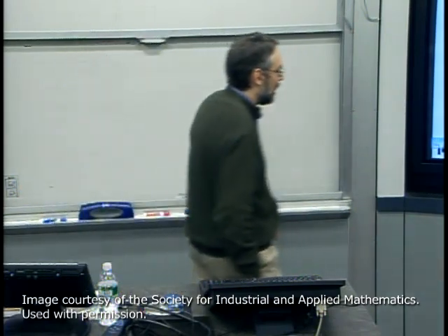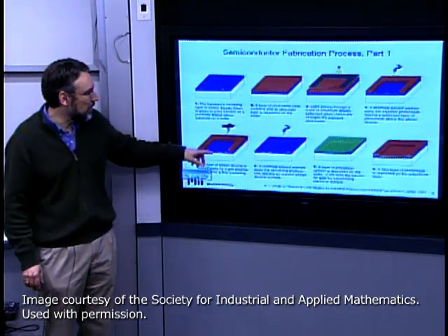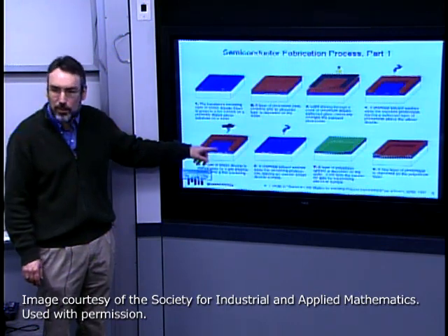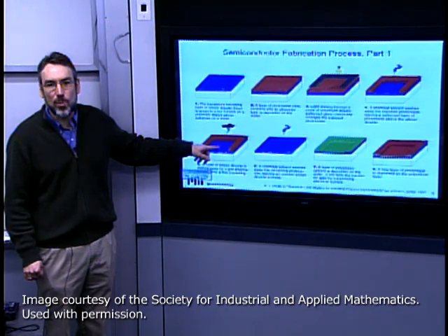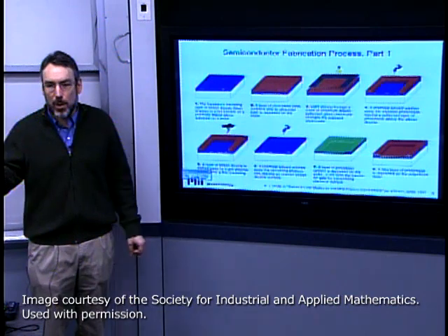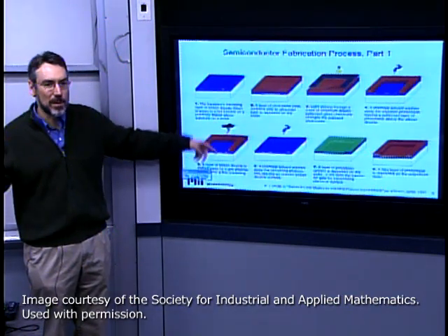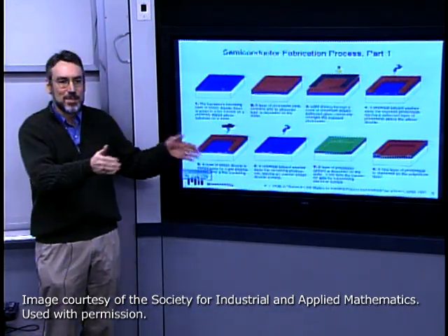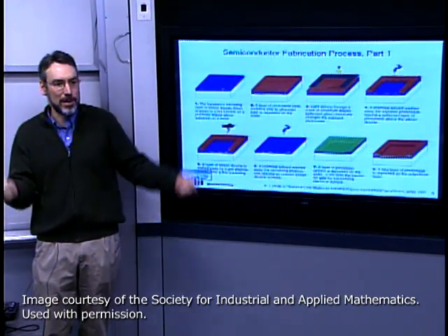At present, at least, and there are some additional reasons why one wouldn't want to do it, but at present we don't have the observability to be able to know when we're within 100 angstroms. Second, there's no way you could be that uniform across the whole wafer. I mean, what if on one part of the wafer, instead of 5,000 angstroms, it was 5,001 angstroms? By the time I get down to etching 4,900 angstroms everywhere, that little 1 out of 5,000 controllability has been